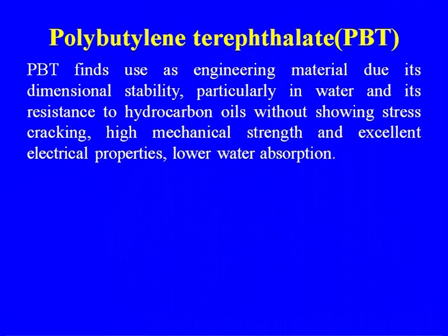This PBT finds use as an engineering material due to its dimensional stability, particularly in water, and its resistance to hydrocarbons without showing stress cracking, high mechanical strength, excellent electrical properties, and lower water absorption. These are some of the advantages of PBT.